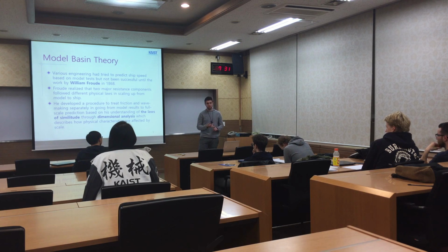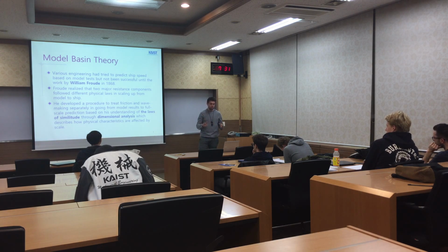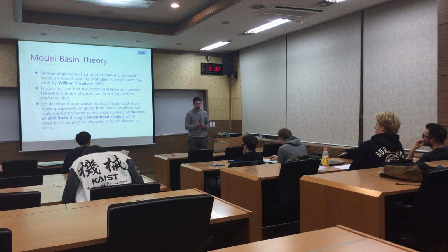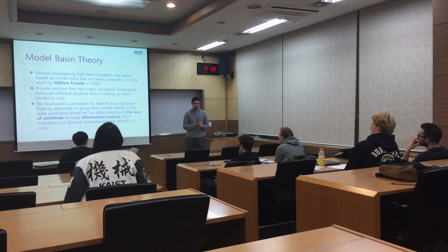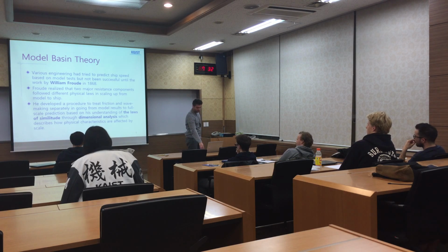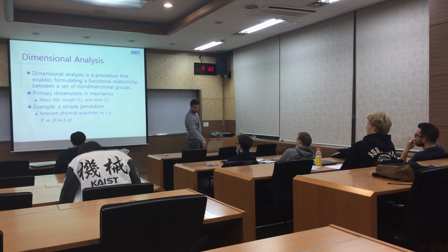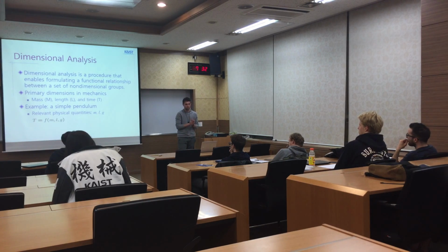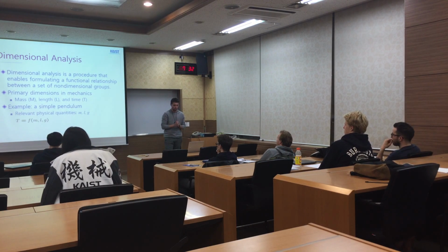They behave totally differently when scaling up from the model size boat to the real size ship. So he developed a procedure to treat the friction and the wave making separately. And he did this by understanding the laws of similitude through dimensional analysis. The laws of similitude describe how physical characteristics are affected by scale. That's the main idea. And dimensional analysis is a procedure to formulate functional relationships between a set of non-dimensional